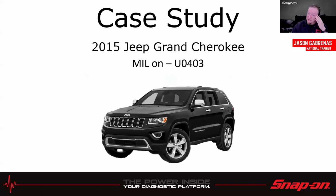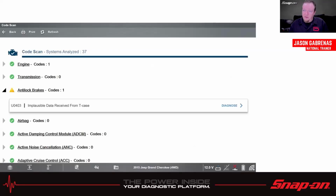So now we have a little case study to talk about bus problems. This one's a little unique, and I think it's a pretty good story about that. This is a 2015 Grand Cherokee with a U0403 code. That's a communication code with the transfer case. It says implausible data received from transfer case. Usually this doesn't throw in the engine; it will throw in the ABS or the transmission usually.